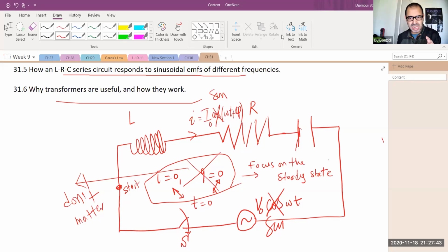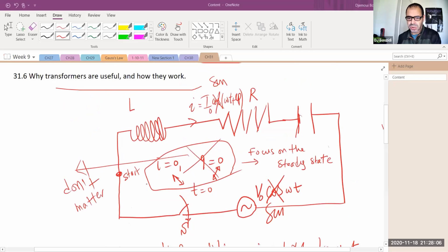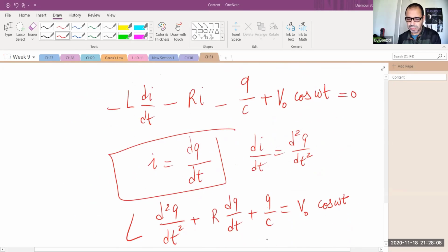The reason why is because I'm going to take the derivative of everything in here and deal with the current instead. If you like the cosine, just add 90 degrees to it and you're fine. If you don't like what I did, the cosine actually is a sine shifted by 90 degrees, so you'll have everything plus 90 degrees everywhere. It's the same thing, and then you don't have to deal with that negative sign. So this will become just sine of omega t. Everything else stays the same.